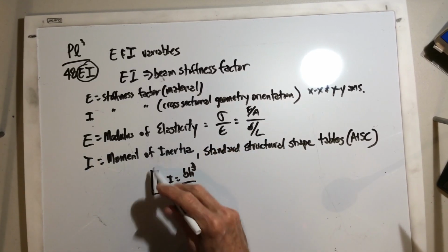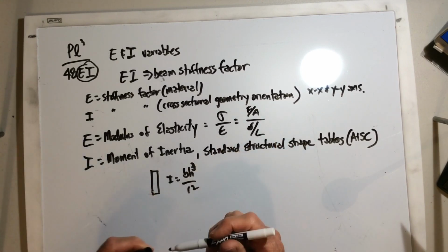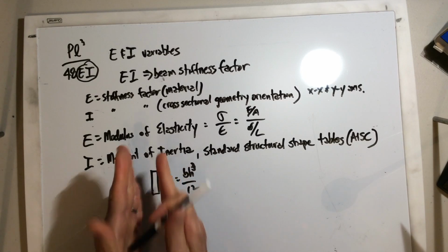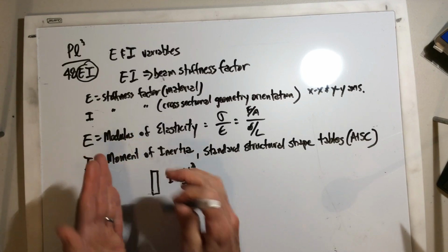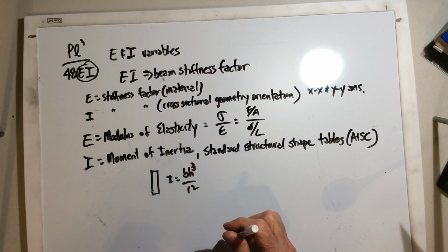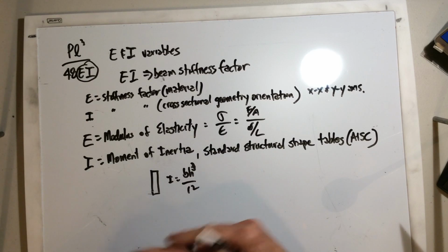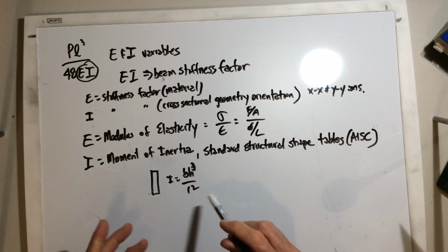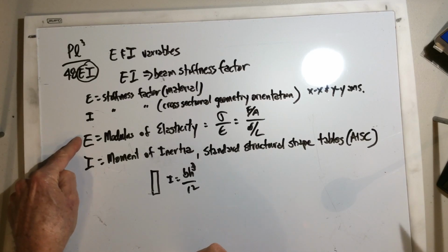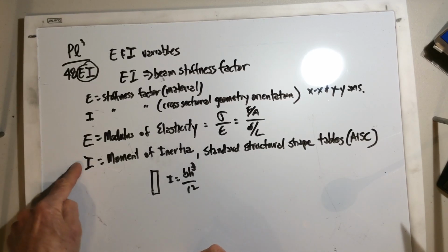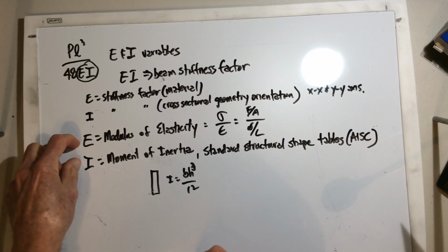Okay, for that orientation. Now, if you turn it over around, then you still use this, but then the base and the height change, and you can see its stiffest orientation is the vertical, going this dimension vertically. This is a 2x6. This would be 6 inches. So you can see laying down the other way would be much weaker. The values would decrease. So these we're looking at maximum values. The greater the value, the more resistance to bending, or the greater the stiffness is.